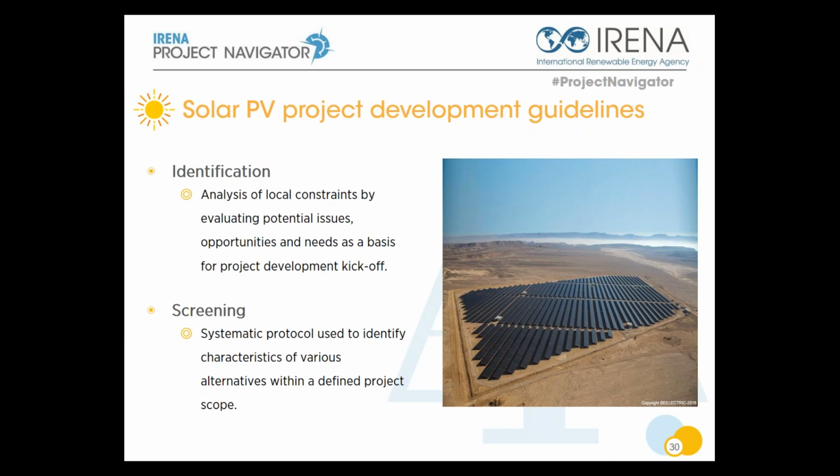In the guidelines, we recommend that the slope profile of a terrain must not exceed 10%, and often banks will go as far as 6% as a success criterion for a solar PV project.